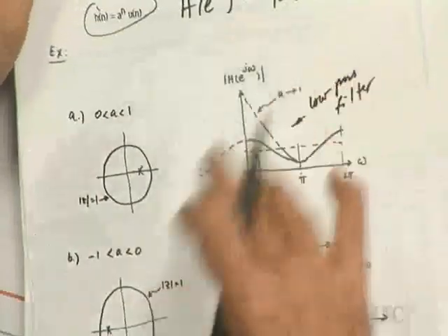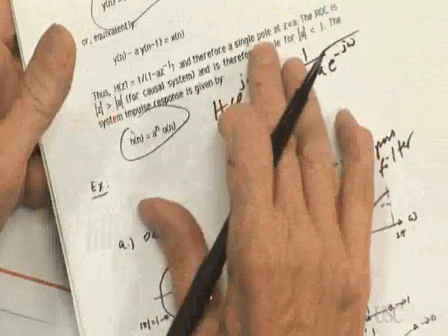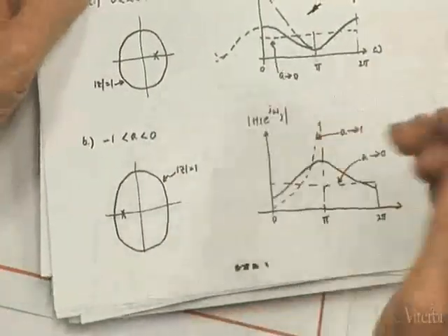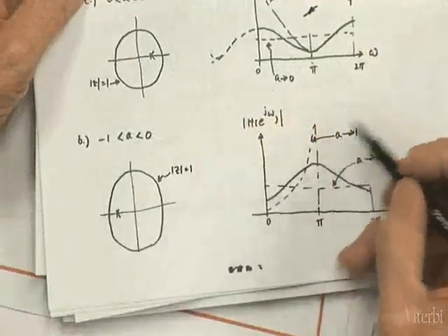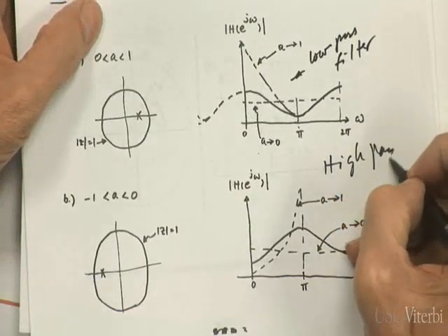So that's why people like these simple recursive filters. I use these low-pass filters all the time if I want to do some simple smoothing. And if you may recall, if a is negative, then you get something that we called a high-pass filter.